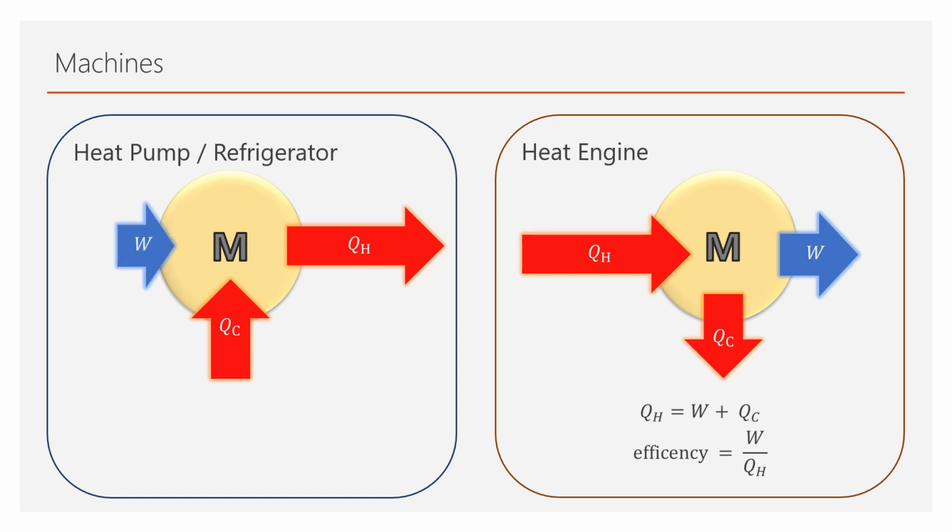Just like before, the total input energies must be equal to the total output energies. In the case of a heat pump, the input energies are the work and the heat pulled from the cold reservoir. The output energies are the heat that is dumped into the hot reservoir.